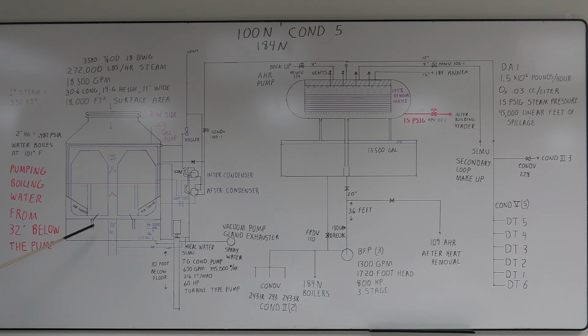That's kind of an important point on these. Even though the water is cool, by our standards, inside here it's boiling. One of the problems with vacuum surface condensers like this, you're pumping boiling water from 32 foot below the pump.